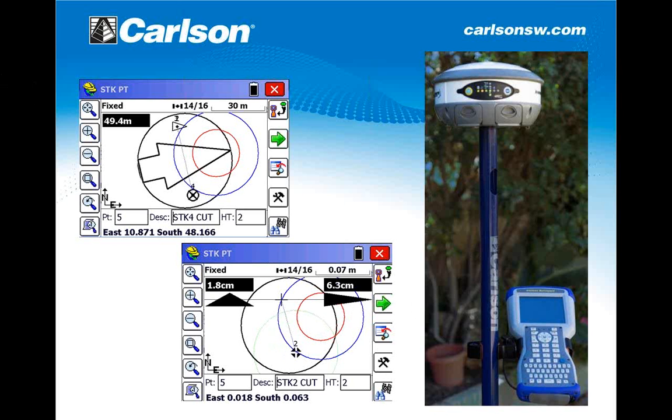So what are the features that will be coming from this? Well, of course, the sensors in the unit require calibration, right? This is something we have learned, and all the users will be learning along this year. SurvCE has already included a calibration routine that I can show you later for the tilt sensors, a very easy calibration. When it comes to more complex sets of sensors, the calibration routines are more complex, because there are several devices that have to be calibrated.